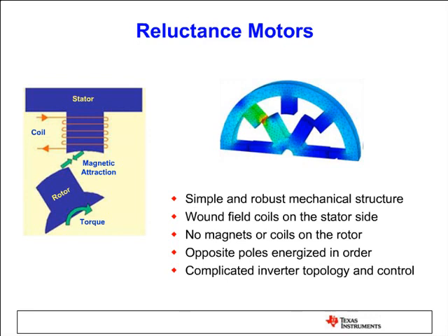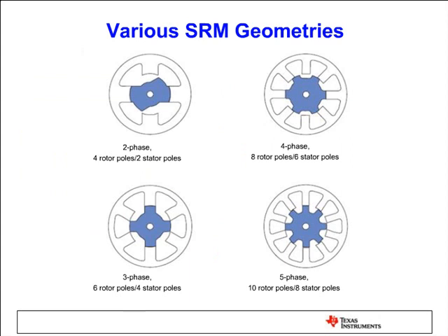The basic philosophy is minimizing the reluctance, or in other words, when we excite the coil, the stator pole becomes sort of an electromagnet, and the rotor is, of course, metal, and that's why the metal is attracted by the electromagnet on the stator side. That's how switch reluctance motors spin. These are relatively cheap, very robust. I won't say they have high power density because we need to again create our own flux.